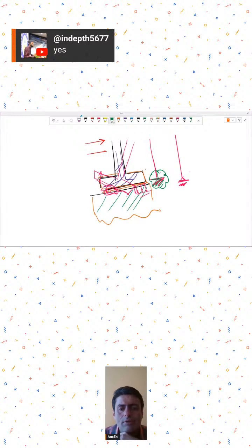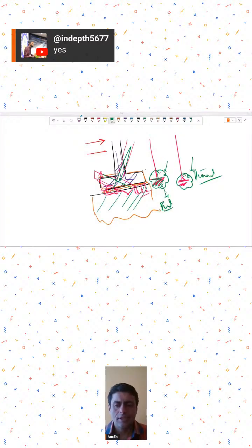So at that point, what is happening? This system undergoes a rotation. So if it undergoes rotation, then engineers or book writers think that it can be idealized as a pinned condition. In general situations, it is more like a fixed condition. In this kind of a situation, it is more like a pinned condition.